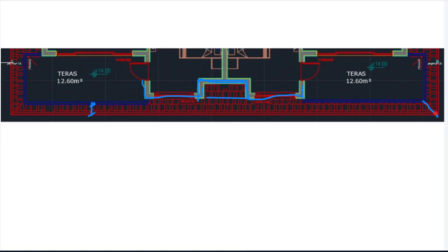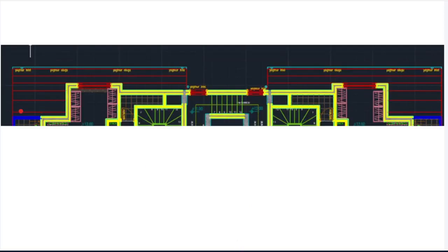This corner, that most of you did forget to put this 45 degree that we want to see. These 45 degrees are missing in your project. We need to see them. Please consider these setbacks in order to have a nice view in your project, and respect at least 30 centimeter or 1 meter. It depends on you in your design. Those setbacks. And this is, as I mentioned, the roof plan of cylinder type, arch type.